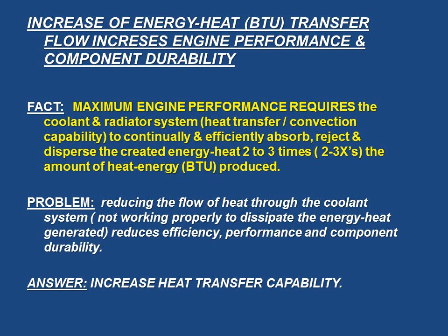Here's the fact. Maximum engine performance requires the coolant and radiator system, in other words, heat transfer, to continually and efficiently absorb, reject, and disperse the created heat energy 2 to 3 times the amount that was produced. Problem is when you reduce the flow of heat through the coolant system, in other words, it's not working properly to dissipate the energy and heat, it reduces efficiency, performance, and component durability. We have to increase the heat transfer capability.